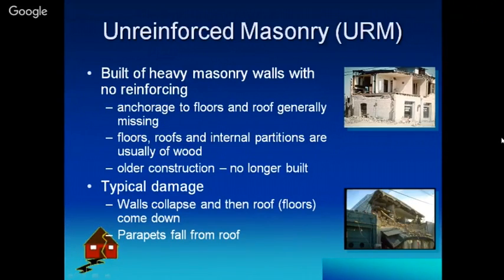Due to these we have out-of-plane failures, as you can see in the top right corner image. The complete house is intact, vertical elements are intact, but your horizontal elements, which are the walls, are falling apart, falling out, which is called out-of-plane damage.